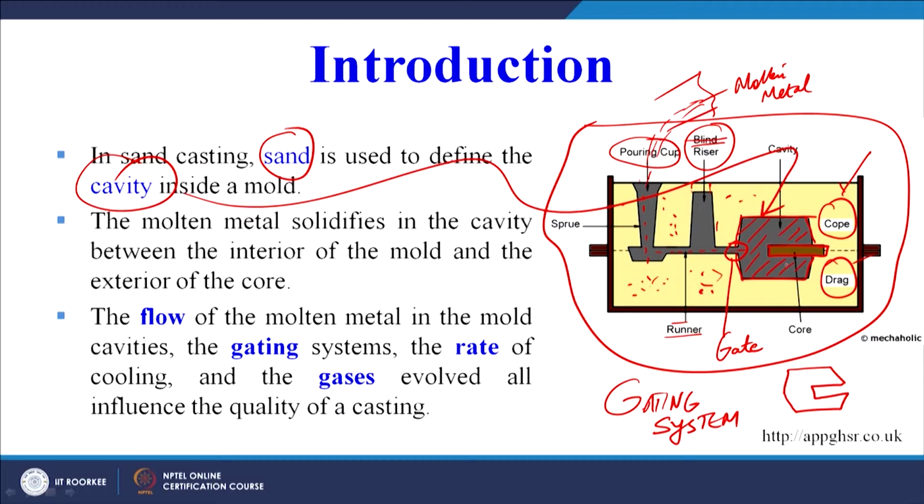So, the metal will solidify exterior to the core and interior to the sand mold. So, this is the sand, on all sides there will be sand, and the metal will solidify on the inside of the sand and outside of the core.